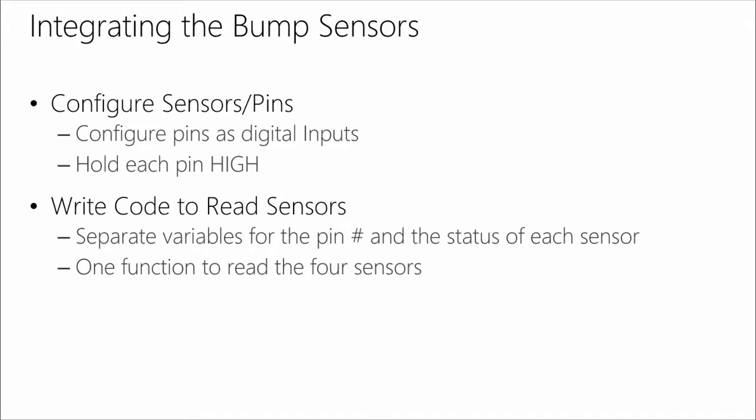Sensors and pins, configure them. We've done a lot of that, Paul. Sure. We have. We've already done that. But basically, you just tell it what pin you're using. It's a digital pin because we're gonna read it. We hold it high. Remember how we did that? We did the digital write to hold it high. That uses the internal resistor on the Arduino board to hold it up high until it gets pulled to low, pulled to ground, right? Which the switch does. And again, if you missed that or you're just joining us, check Module 2 out. We talk about all those things in Module 2 when we show you how to program that. So yep. Check that out.